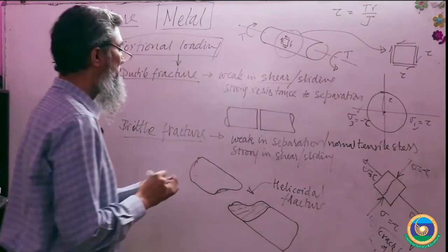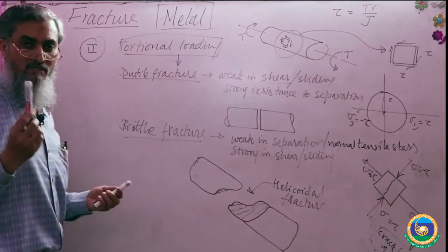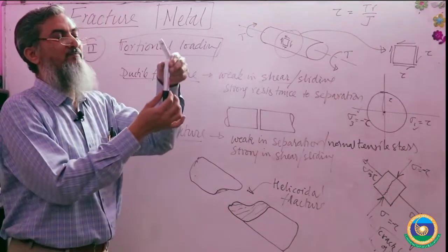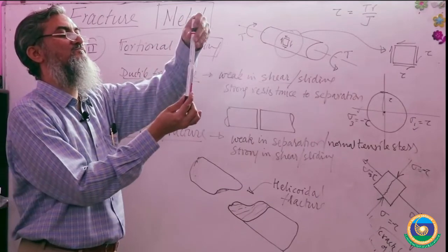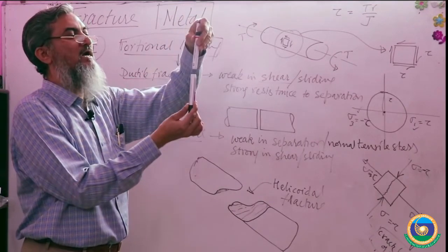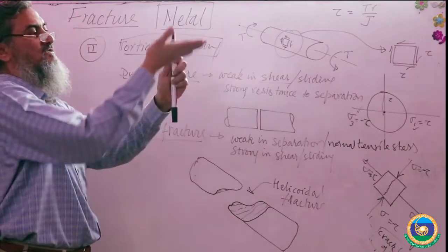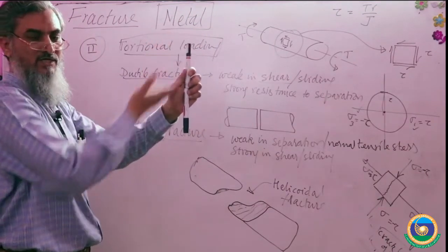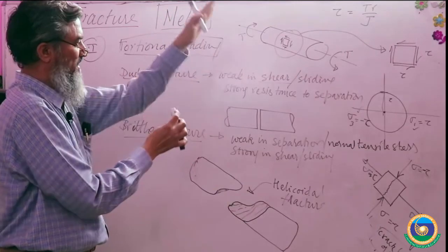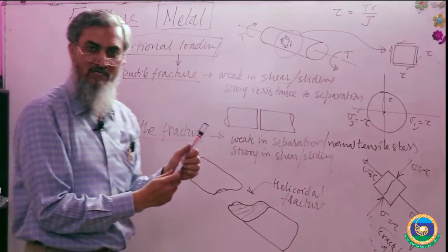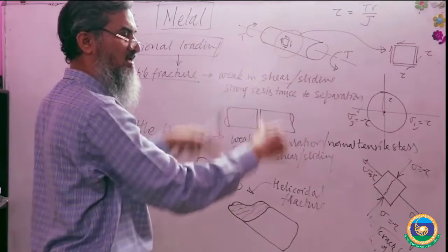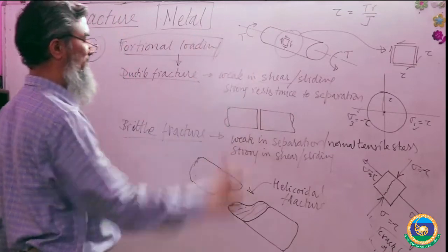So we'll sum up. In the tensile test, the brittle fracture was like this, separation in two parts. For ductile fracture in a single crystal, there was a shear failure at some angle like this. And when it was a polycrystalline material, it was a classic cup and cone fracture. There was necking and then cup and cone fracture.